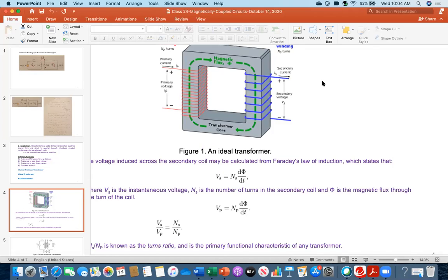750,000 volts. And then again, you put another transformer, and gradually you step down, step down, step down, and finally you get 120 volts at your home. So this means, as an example, that the distance between your home and the power plant could be 1,000 miles. There are even examples of much more than that, at least several hundred miles. So therefore, on the way, there will be a huge voltage drop. That's why you need these devices.